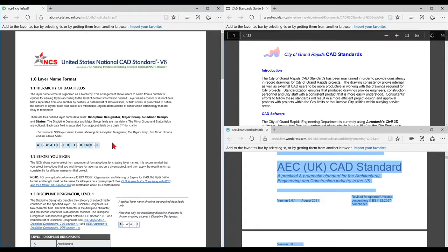So the first planning is layers. You need to make sure what layering you have, and then you get into different types of text styles, dimension styles, and other blocks, symbols, and whatnot. We're not going to cover symbols, but the idea is to pre-populate your documents, having a document that everybody can start from that has the settings correct from the get-go. By no means is this all-encompassing. I'm trying to cover as much as I can today.